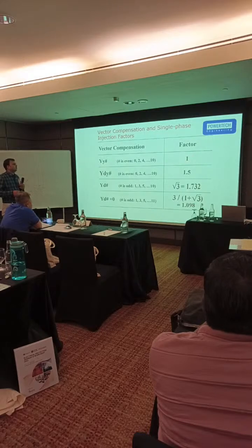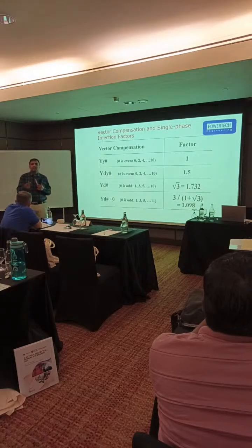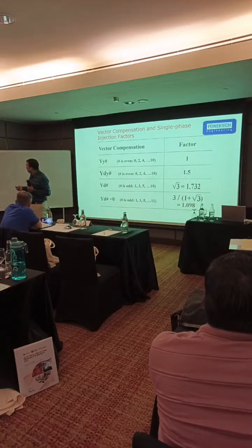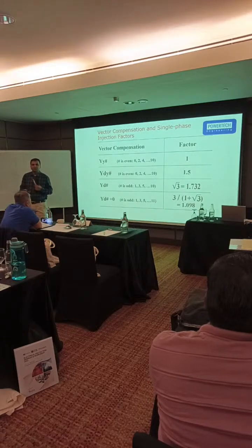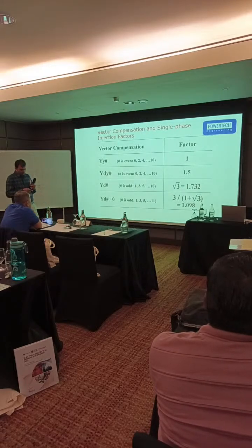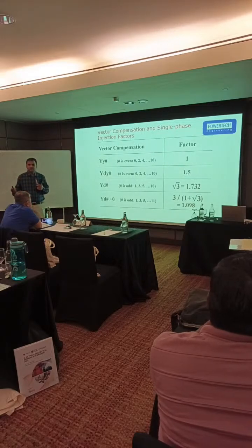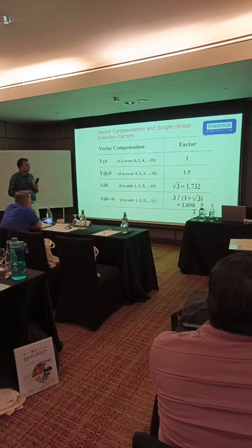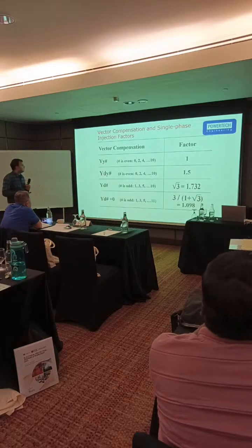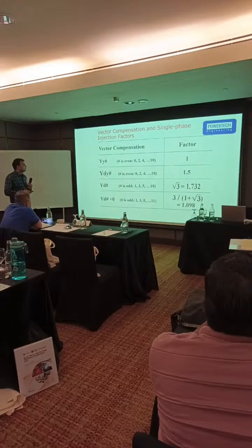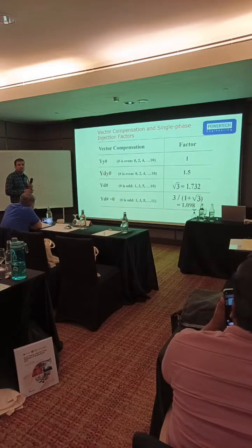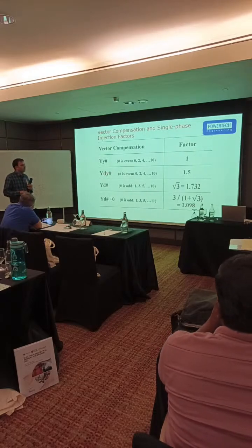In any differential relay you test, either you will find the factor is 1. If it is a delta winding, then the three phase and single phase pickup will be the same. If it is zero sequence elimination in a star winding, then you will find this condition. We set it in the software as YD with D for eliminating the zero sequence component.